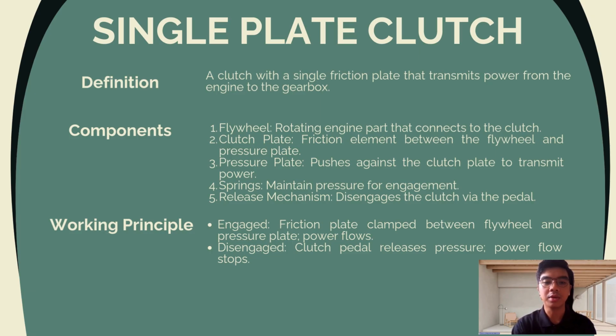So for the working principle, in the engaged state, the clutch plate is pressed between the flywheel and the pressure plate to transfer power. When the clutch pedal is pressed, the disengaged state occurs, separating the clutch plate from the flywheel, stopping power flow and allowing gear changes.